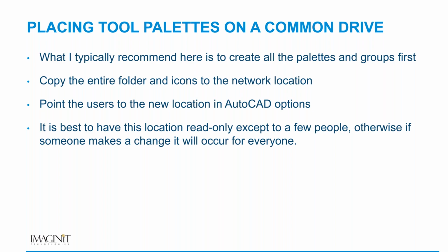Yes, I know, David. Double stress the read-only. I cannot tell you this enough, you have to have your tool palette location set read-only, except to one or two people who can make changes. Because if somebody makes a change to their tool palette and they have write access to that location, it will affect all other users who point to that same location.